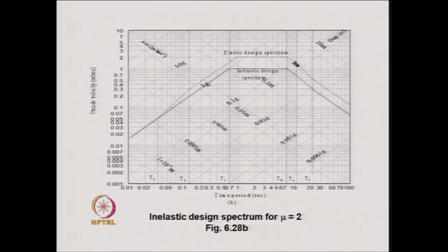So, that is how one can get the inelastic design response spectrum for mu is equal to 2, then mu is equal to 3, mu is equal to 4 and so on. mu is equal to 1, obviously, will correspond to the value of the elastic design response spectrum.